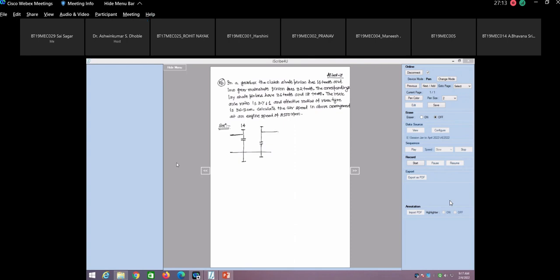सर अभी आपको समझना चाहिए. This will have 36 teeth. This will have 18 teeth. This will be 32 teeth. Because please note that to keep the center distance constant, you have to have the sum of the teeth to be equal. That means the 14 plus 36 comes out to be 50. 18 plus 32 comes out to be 50. So these have to be there.